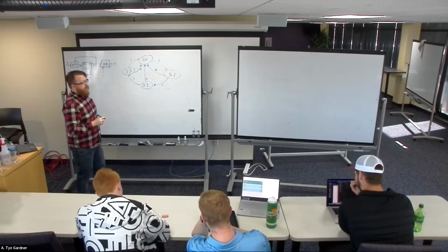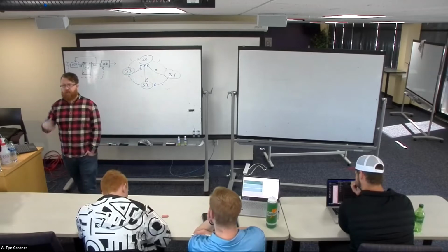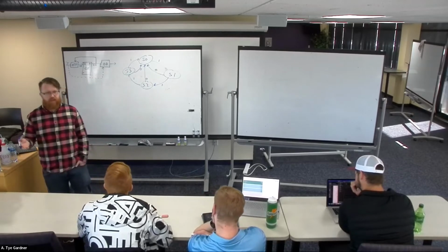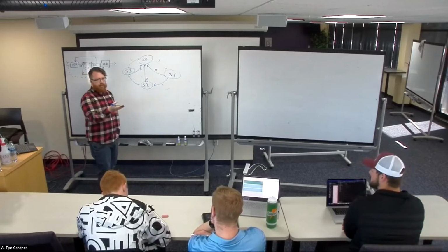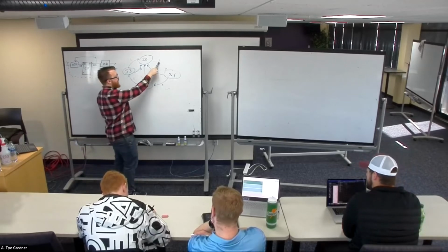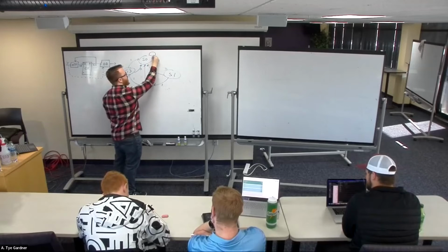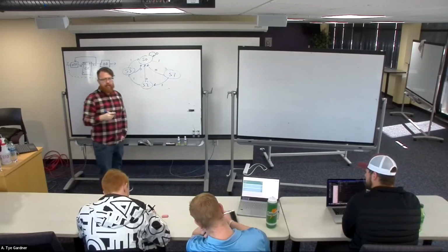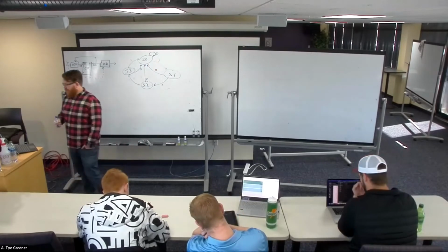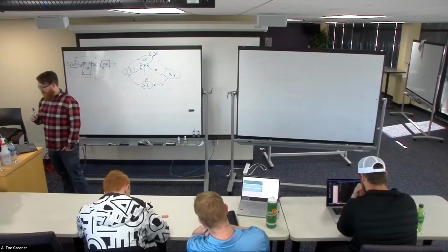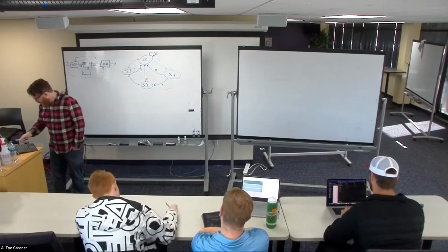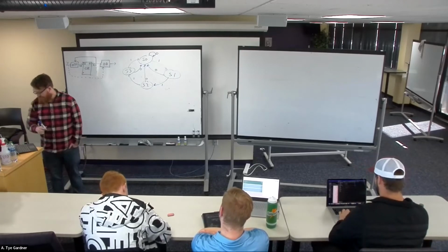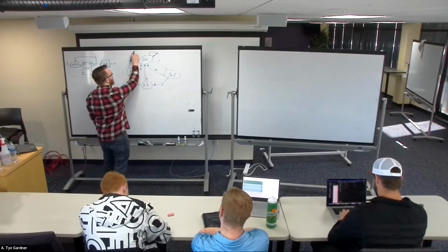And then we go and check, right? There's a sanity check on this. If we want to make sure it's a complete diagram, we just have to check that we have all possibilities covered. I'm missing 1, right? I have the 1 exit here, but I don't have 0. So I need something that says if the input is 0, then we stay put. And then I think the only place on this one that is going to be true is here.